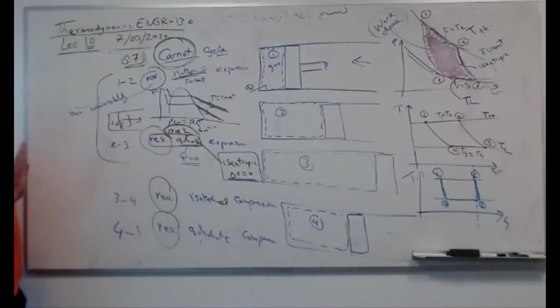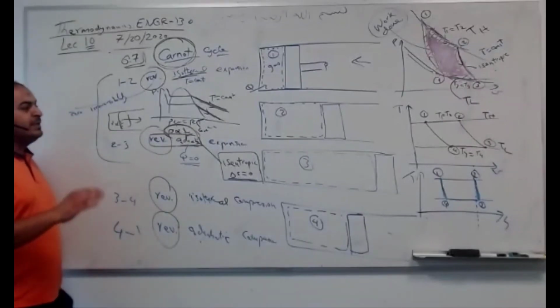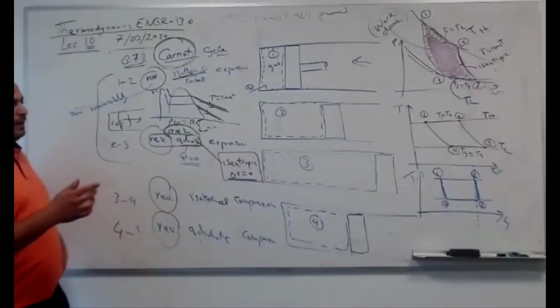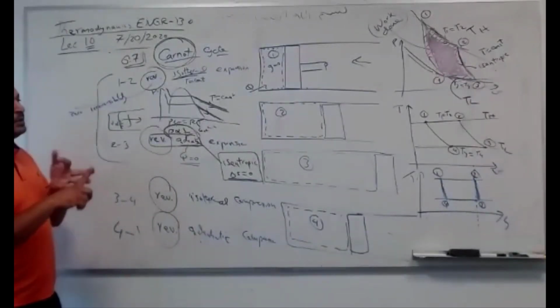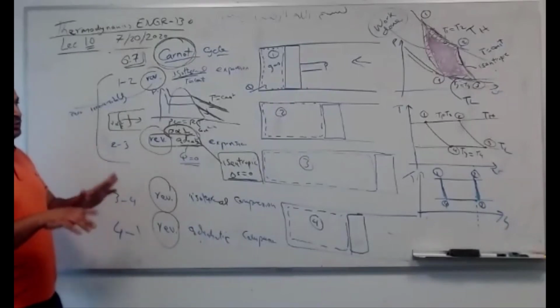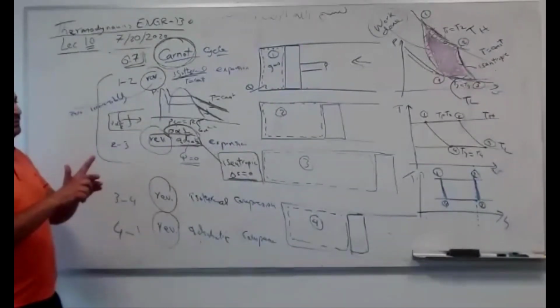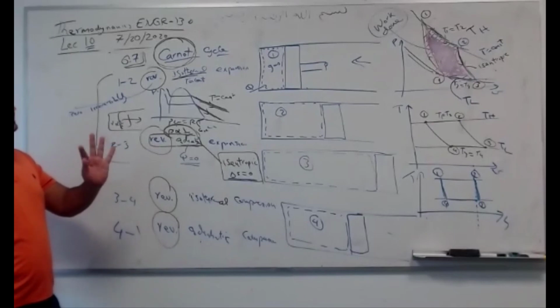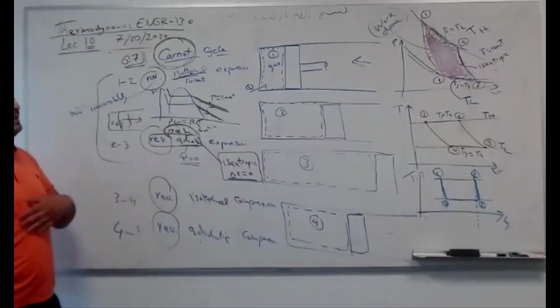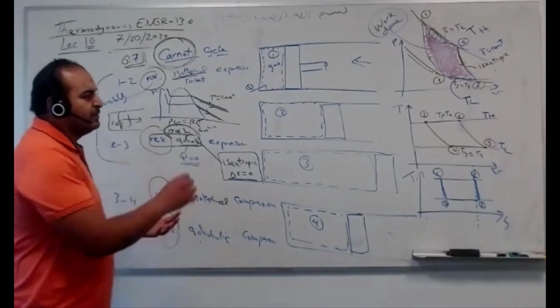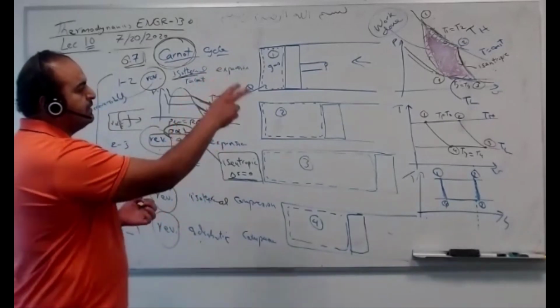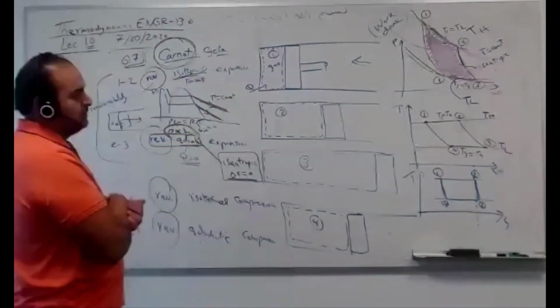But the good news is you need to know how to draw anything: constant entropy line, constant temperature line, pressure line. For now, you need only temperature, pressure, and volume. We're going to add entropy, so we have 4. You're going to draw anything from these 4: temperature, isothermal; volume, isochoric; pressure. So you need to know how to read the problem and draw it in PV, TV, TS.